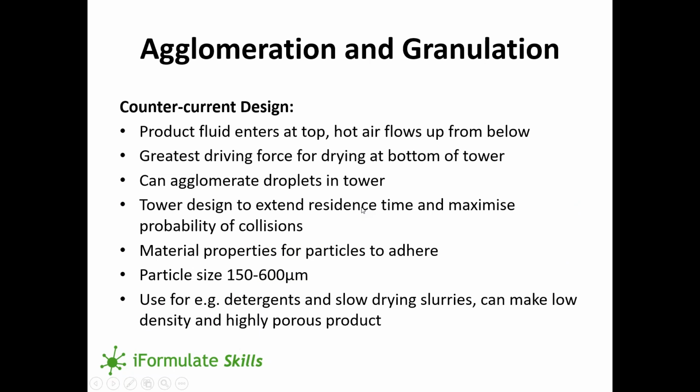So earlier I promised to mention agglomeration of particles, and one way of doing that is in the spray drying tower itself, and here you would need probably a countercurrent design of spray dryer. And in a countercurrent spray dryer, the product fluid enters at the top, but the hot air, the drying gas, flows up from below. And that means that the greatest driving force for drying is where that hot air is hottest, and that's at the bottom of the tower.